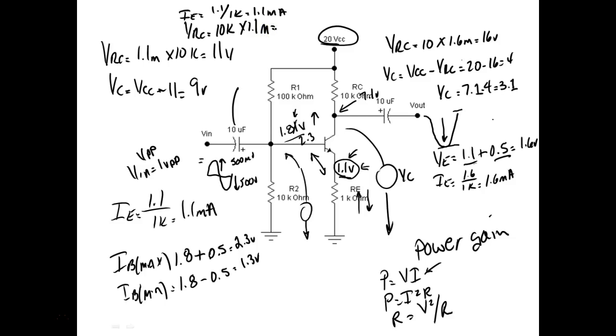Because what we're doing is we're assuming that IE and IC are equal to each other. Are they equal to each other? No, but they're so dang close. Dealing with the tolerance of the resistors, they're close enough to give us a very good calculation, right? So that means it would drop how many volts? 11 volts, right? That makes sense? Okay.